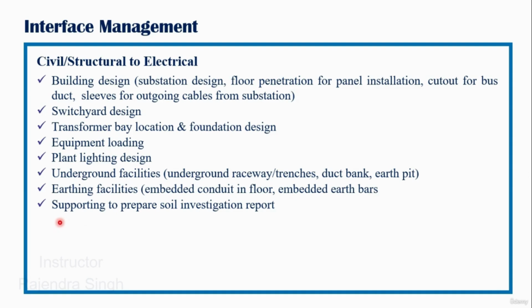Then support to prepare the soil investigation report. Ideally the civil team hires a consultant for the soil survey. So in that soil survey, we have to provide input to the civil team that by Wenner's 4-pin method, we have to receive the soil resistivity data in order to proceed with the earthing design. That data is also provided by the civil team. The complete soil study report, wherein the resistivity information done through Wenner 4-pin is also mentioned, is taken as input for the earthing design.